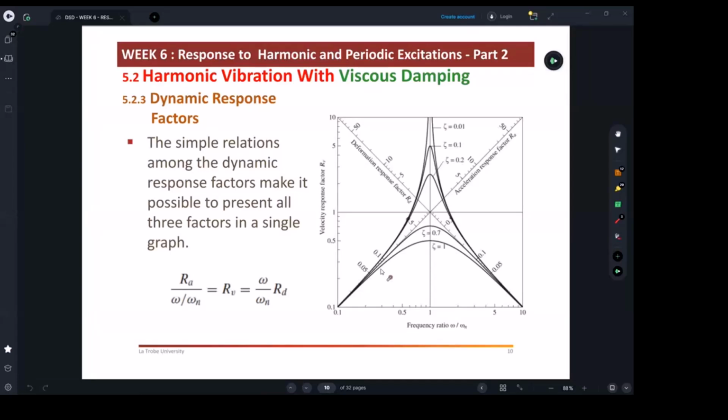So you have to set up your experiment in a way where you would make your structure get excited and maybe get it to reach resonance. So how you're going to determine those values, you need to make sure your displacement sensors or accelerometers will actually be able to measure this as well. You can't just apply values without making sure your measuring device can actually read it.